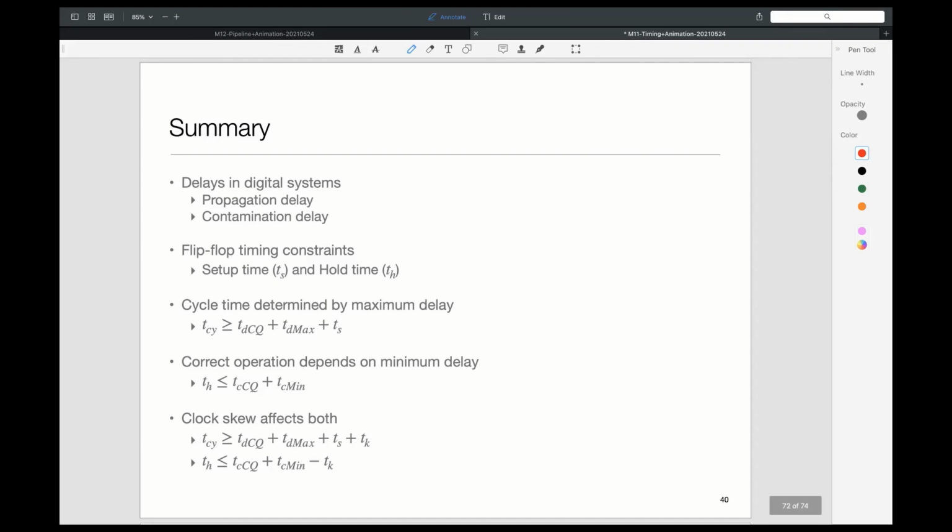And we have these two equations, which you really, really absolutely must try to understand. Like I said, you will have questions on this in the quiz. So one is hold time and the other is setup time related. Setup time related, I can always deal with by slowing down the clock. That may not be desirable, but at least your circuit will work, at some clock speed.